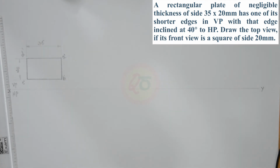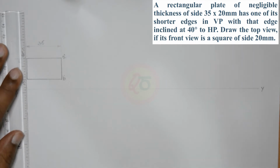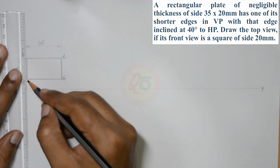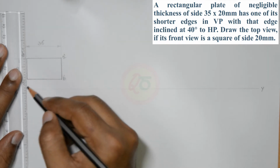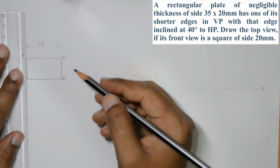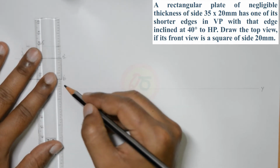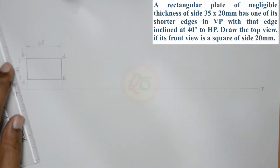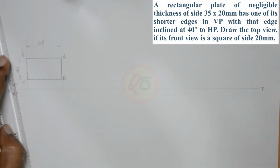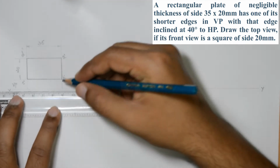Now, in order to obtain the top view, which is a straight line, the plane resting on VP will be seen as a straight line. Take projections from A dash, B dash to the XY line. Darken the segment on the XY line where the projection lines intersect.